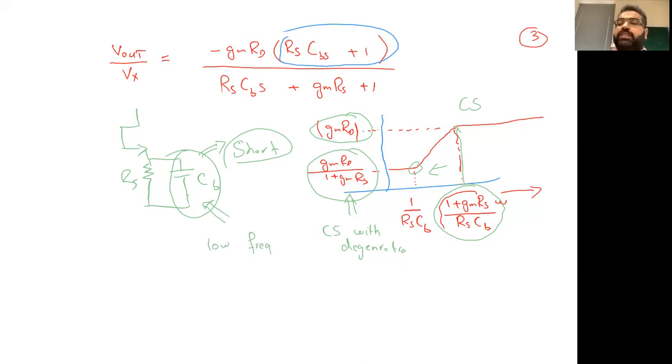तो सिर्फ C in low frequency capacitance नहीं होता, also we have another capacitance जो कि यहाँ इसको commonly कहते हैं bypass capacitance. Bypass capacitance, that's also a low frequency capacitance. तो हम लोगों ने analysis point में कहा था, for the low frequency analysis we will consider the capacitance, we will identify them, but in the mid band calculation and in the high frequency response we will do them short, ignore them, meaning we will do all of them short. Short meaning zero कर देंगे, RS in parallel zero is going to be zero. Okay, so till now we have seen the low frequency response of a common source.